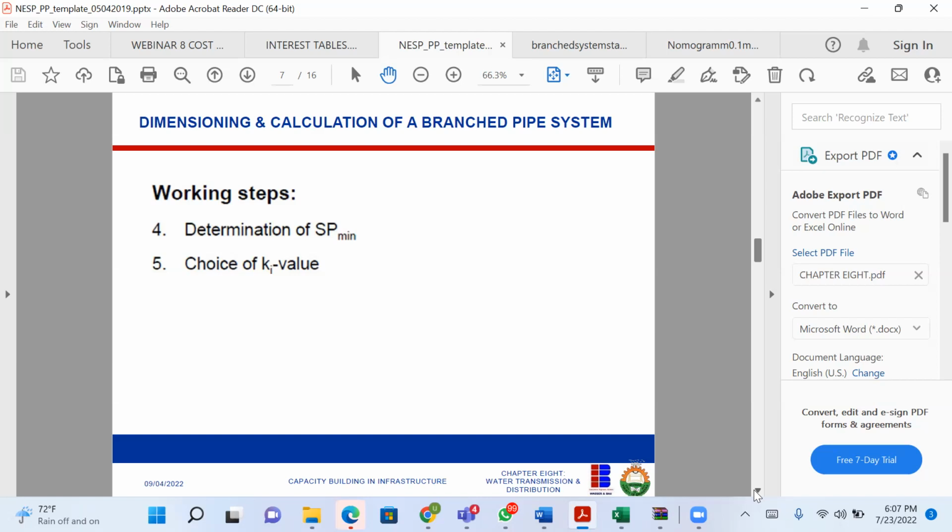That's why in Abuja, for those of you that know about Abuja, you cannot design more than a 12-story building in some areas. The reason is that the tank supplying water to Abuja cannot supply water to a house that is more than 12 stories. But that does not mean you cannot build it, but you need a special approval, meaning you're going to develop your own water or build some pumps so that when you take water from the public supply, you push it up and then it flows back by gravity. So if you are doing a 12-story building in Abuja, you're on your own, because the municipal water supply will not service you without the aid of pumps or additional conditions.